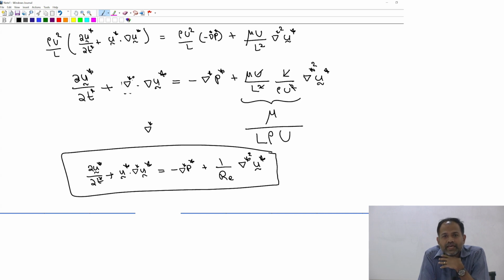So you are actually ending up with different solutions based on one non-dimensional parameter. It doesn't matter what the size of the pipe is, what the fluid is, it only matters what the Reynolds number is. That's what the non-dimensionalization of the equation has just said. Clear? Should I repeat?